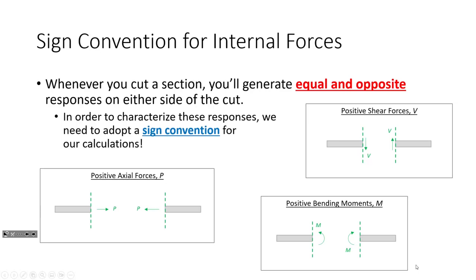You probably don't really know what I mean by that. That'll become much more important when we look at deflections. When you do a deflection analysis, you have to actually analyze the truss twice, and as long as you're consistent with whether tension is positive or compression is positive, you'll get the same answer. It's just all about being consistent.